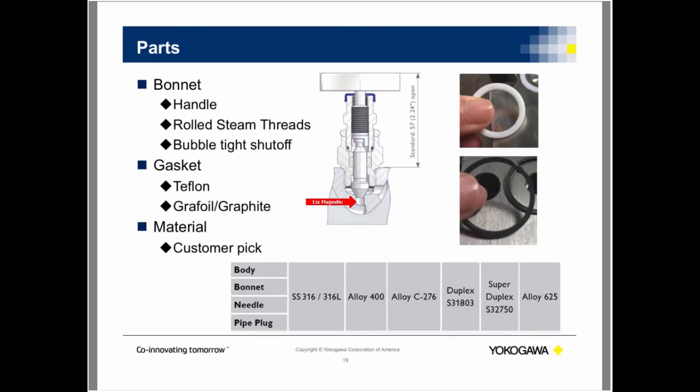Next, we're going to talk about the gasket. Now, gaskets generally go for the flange by pipe, pipe by flange, or flange by flange. Gaskets can be used in other connections too, but those are the three most commonly used. Teflon is very, very common, but it has a limitation on temperature. Generally 450 to 500 degrees Fahrenheit is the temperature max on a Teflon. If you go anything over that, you're more than likely going to melt that Teflon.